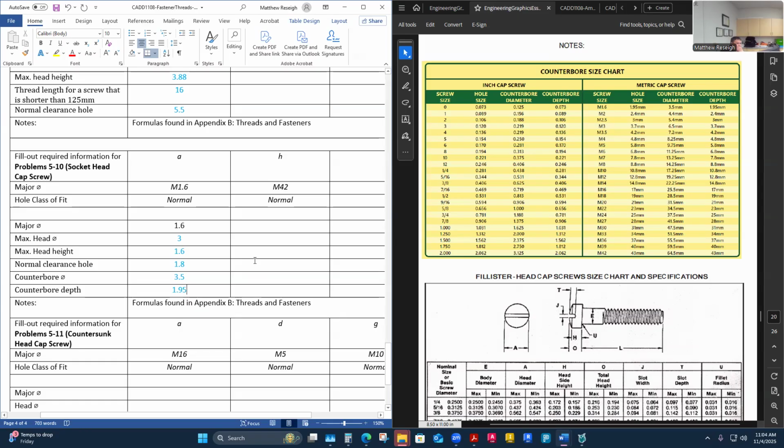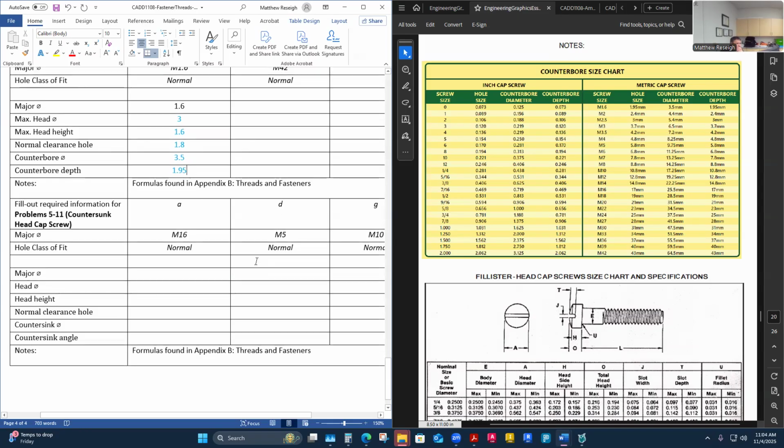Yeah, that's that one. We got one more, right? Yes, the countersink style, the angled one that we already determined is going to be at 90 degrees. We just looked that up. It's 90 degrees plus or minus 2. Is that what it said? I'll look it up for sure, but I'll at least type it in and come back and put the range in. It probably has the same issue on countersink diameter. It's got to at least match the major diameter, if not be a little oversized.